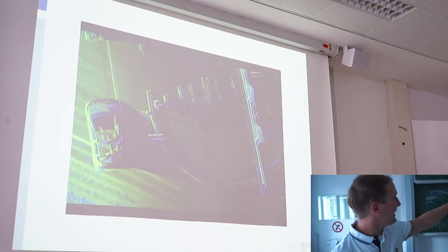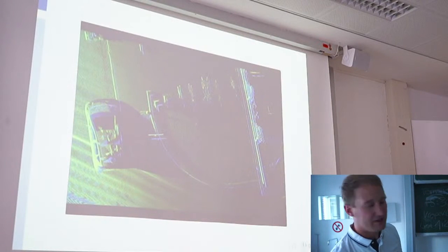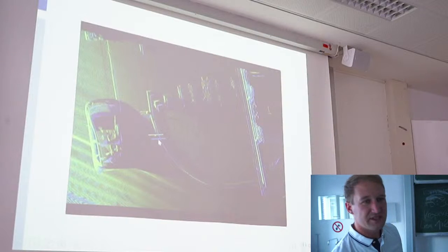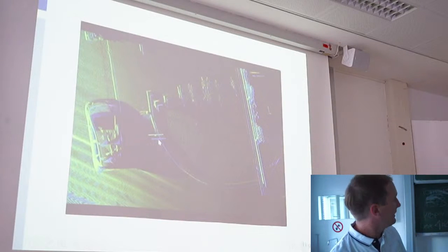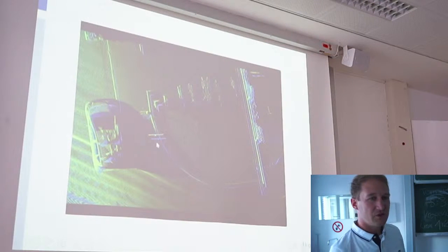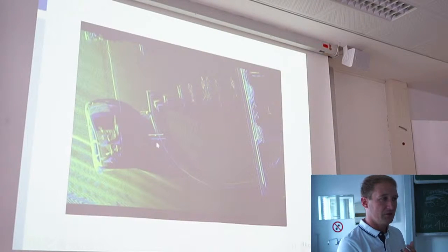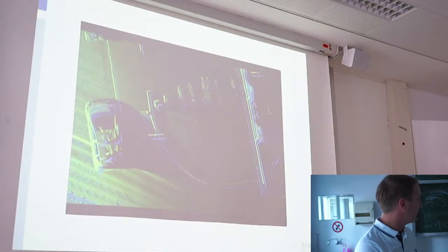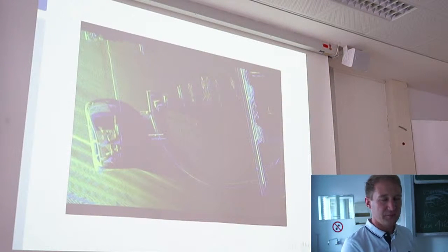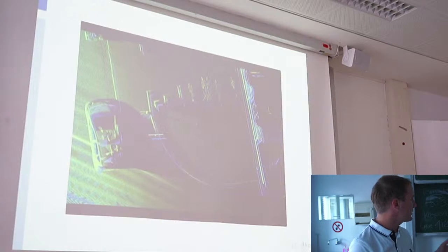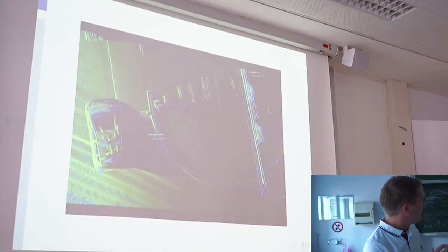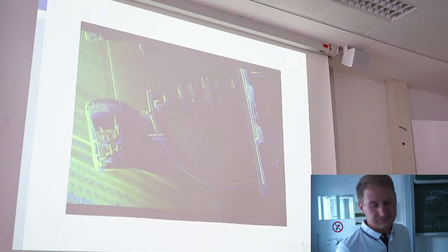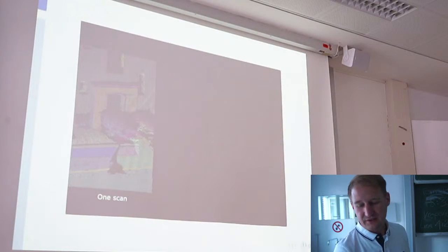So for example, the sign next to this car here, you can't see my mouse, but here it is. Here's a street sign, just looking from the top. And you see there's a small shift because the position of the van is not the same anymore. So one task is to make it one, which means you have to remove these displacements, and you use some algorithm which pulls the point clouds onto each other. And then you might have something like this.